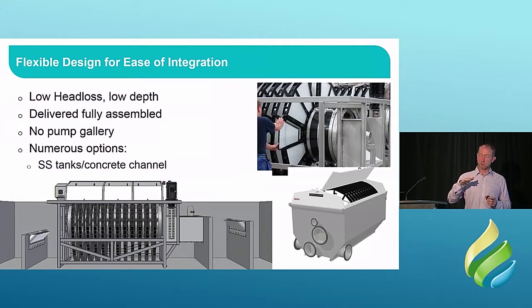Because it's only partially submerged, they don't get installed very deep, so if you're doing excavations, you don't have to go down too far. With our inside-out design, the Hydrotech system, it's fully assembled when it arrives on site and tested before it leaves the factory. So that's another feature of the inside-out. You can put everything on the frame, whereas with the outside-in, that's normally not the case. You'll have a separate pump gallery, and you're going to have to do some on-site installation of pumps and valves and so on.